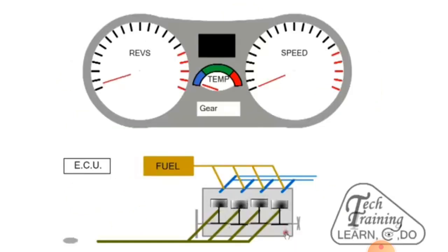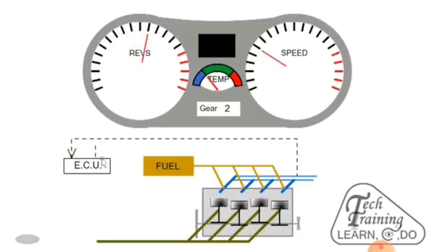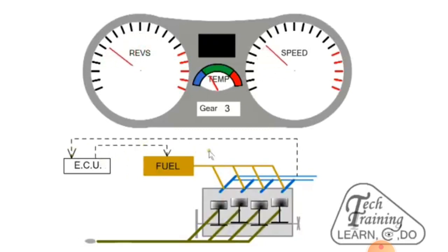Here we see an engine control system in operation. When the engine is started and still cold, fuel injection is determined from the amount of air flowing into the engine. The engine will have additional fuel and run rich. This is called open loop control.